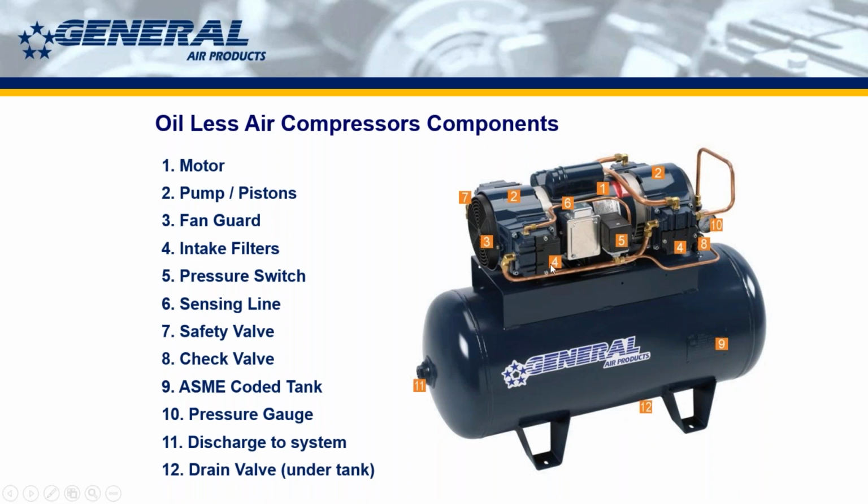And then also notice here number 4. That's your intake filters on these oilless compressors. It looks like a black cap. It's integrated into the head on the crankcase. So it's a black plastic piece there that has our logo on it that unscrews, and you just take that out and you put in new intake filters.